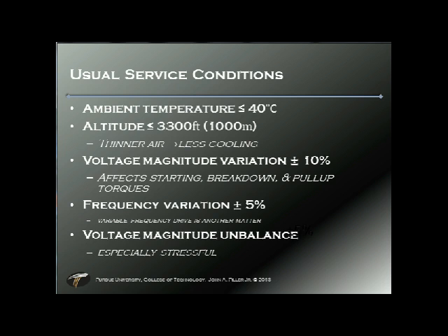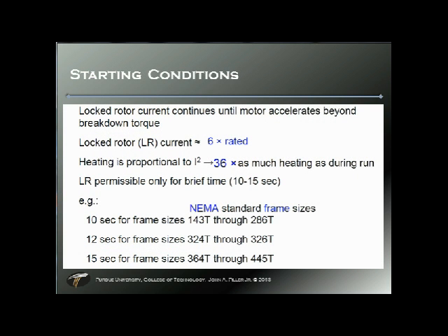Voltage magnitude imbalance, where the magnitude of A phase, B phase, and C phase are different. That can be especially stressful. Alright, starting conditions. NEMA also defines frame sizes, right? Frame size, this would be a small frame, a medium frame, and a large frame range. The frame is the portion that bolts to the machine that you're running that motor with.